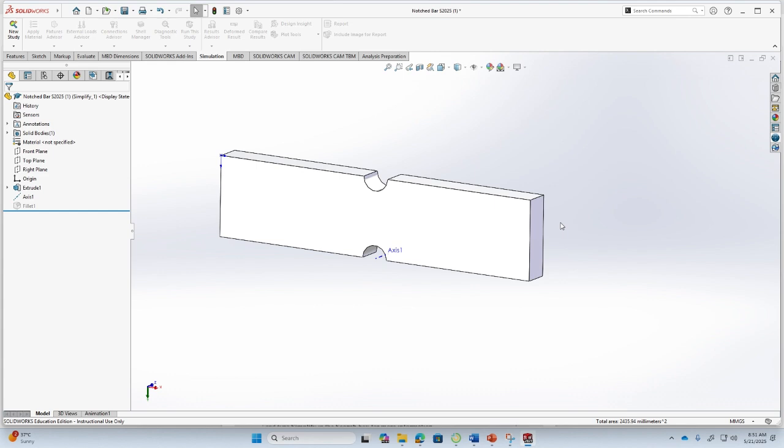In this case, it's on the outer edge, so it will not affect the results significantly. You can try running with and without the fillet later for your own peace of mind, okay. But for now, I will run it in the simplified manner, okay. The justification is that these fillets are on what we call a free surface, okay. So they will only affect the stresses very close to the constrained edge over here, but nowhere else in the model, okay. And even that is not going to be very significant. If anything, they will reduce the stresses, not increase them. So they are actually better for your model, okay, because of the smooth transition at the edge.